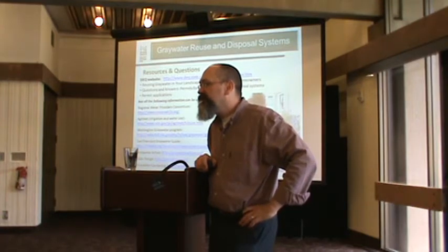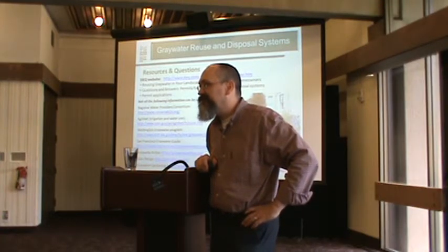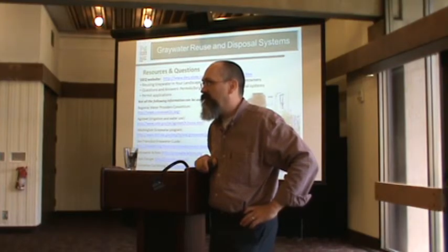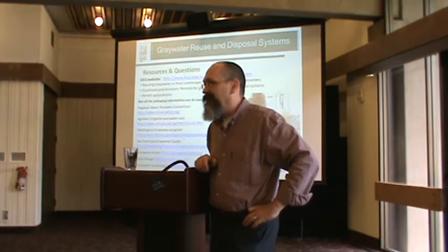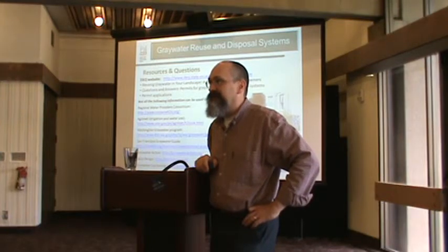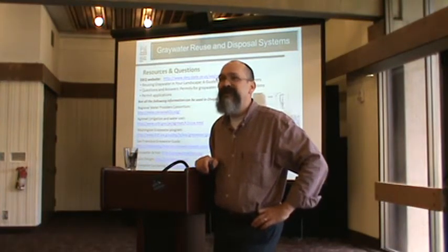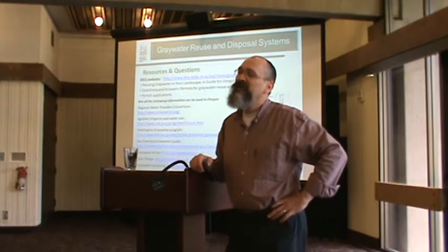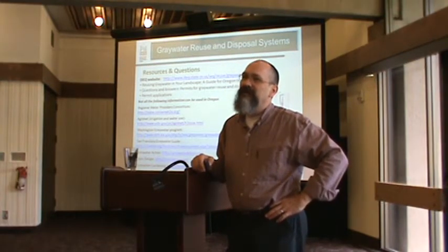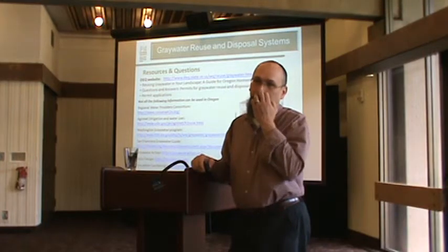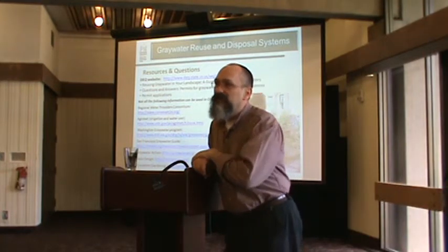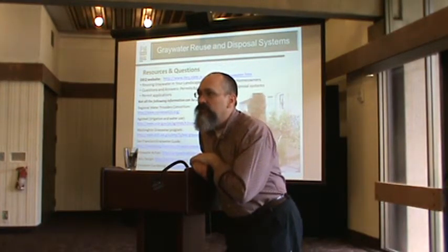So you don't have a sewer connection, or you do have a sewer connection? I do have a sewer connection. So the gray water still has to connect to the sewer system somehow. Right, but if you disconnect it outside the house and connect it to a gray water system, I would have to figure out what the design is. You still have to be able to redirect it back to the sewer if you don't want it to go into the drain field. So we need a valve on it, and that's what they want to check. The three-way valve. Yes. Okay.